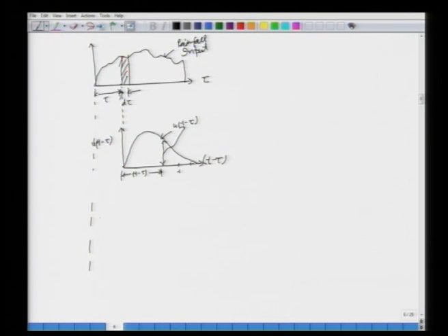All right. So, your response will actually start from time t equal to 0 when this rainfall starts. So, obviously, you have a strip here and the response will start from here itself. Okay. So, this is your time domain t. All right. What is this? This is your q t. Q t is what? This is equal to your direct runoff hydrograph due to all of this input. All right. What is that input? This whole input. Okay. All right. So, I am just going to draw this DRH. Let us say it will look like this.